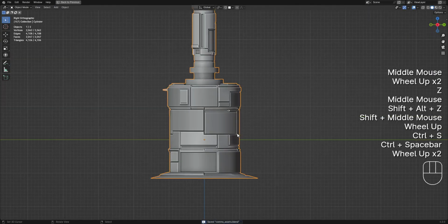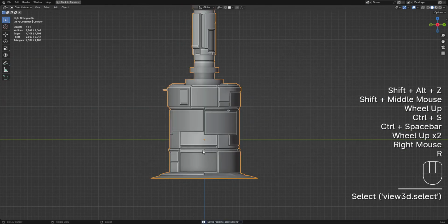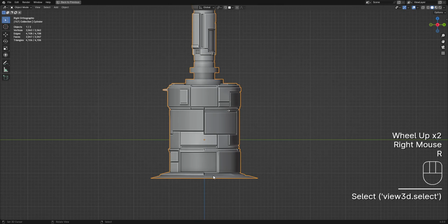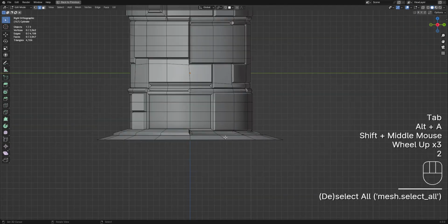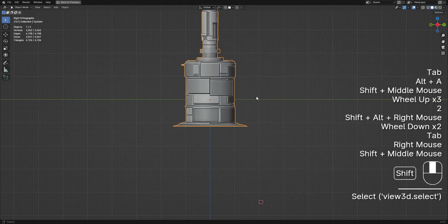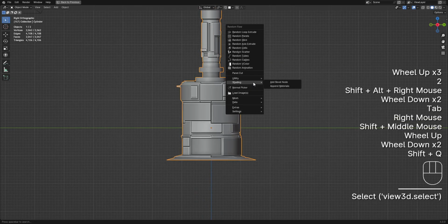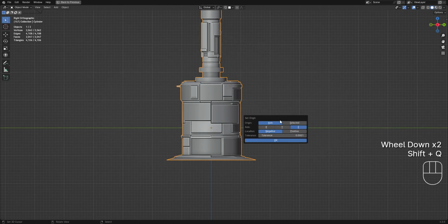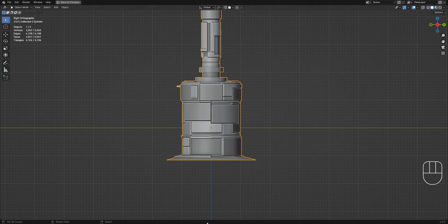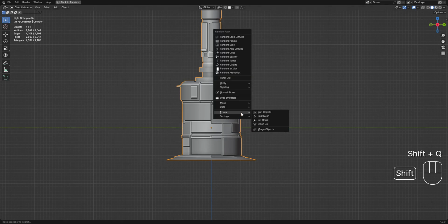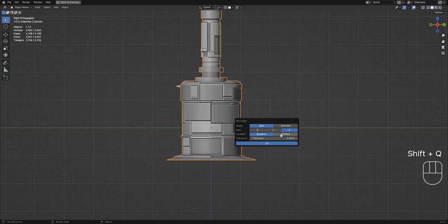Next up, we're going to change the origin to the farthest vertex on the z-axis. So we select the model, then Extra, Set Origin, and it's already set to the z-axis in the negative. So this is the negative z, and that's the positive. Set origin, positive.